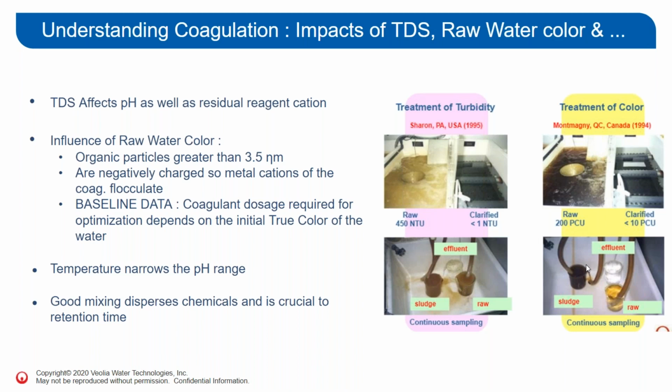But as your turbidity and color, or TDS, increase or decrease, whether seasonal or weather driven, it's going to affect the range of the pH as well. So keep that in mind with the coagulation check, and adding more coagulant for more turbidity is also going to most likely drive the pH down and depress the pH. So good choice of chemical there is important.